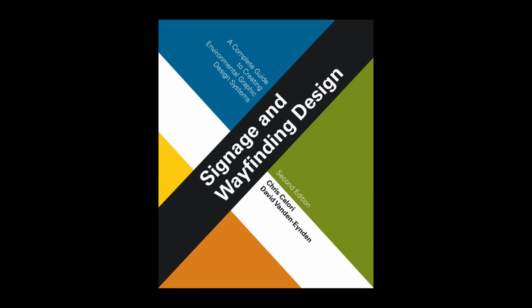In a sustainability note, fasteners are considered more environmentally friendly than adhesives for two primary reasons. First, fasteners don't release noxious solvents or fumes like many adhesives do. Second, fasteners allow easier disassembly of materials for reuse or recycling when the signs have ended their useful life.